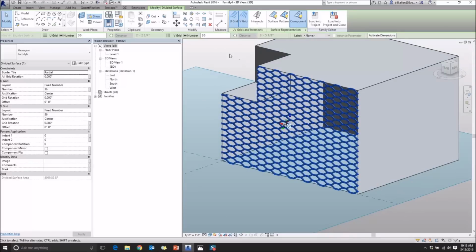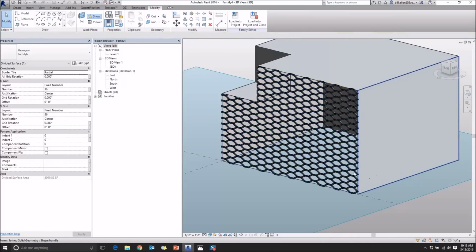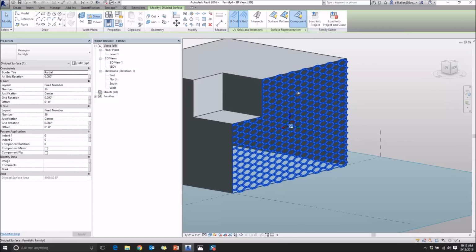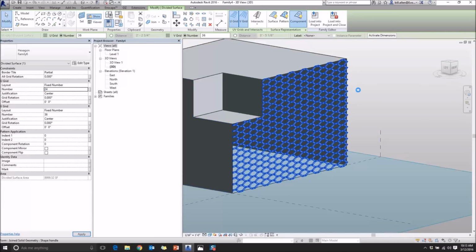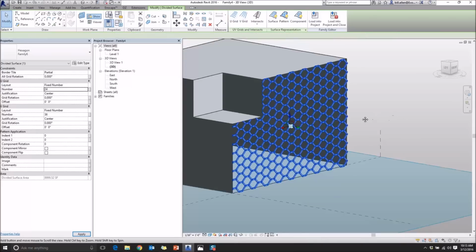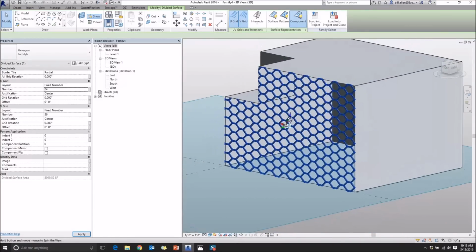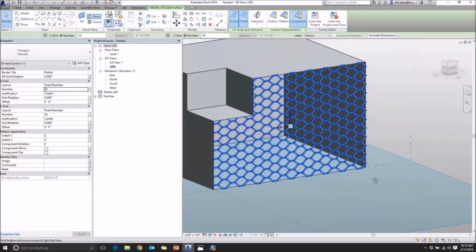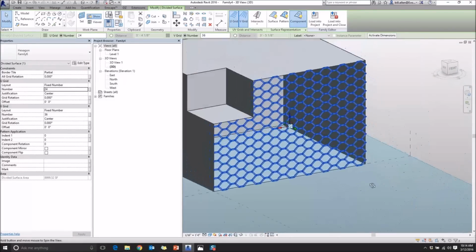You see, it's not just a flat 2D division. This is my frame that I actually started to build. You can do all kinds of things. You can put a solid surface in here, start to develop perforations. If I update this, it updates the divisions on the face here. So this is another really fast way to start studying patterns on the faces of the building, without using any kind of parametric modeling or visual programming. Just very simple, easy patterning in the Revit Conceptual Mass environment.